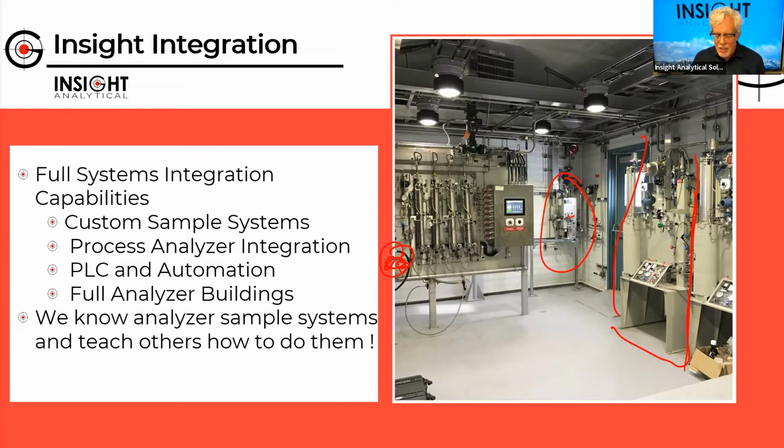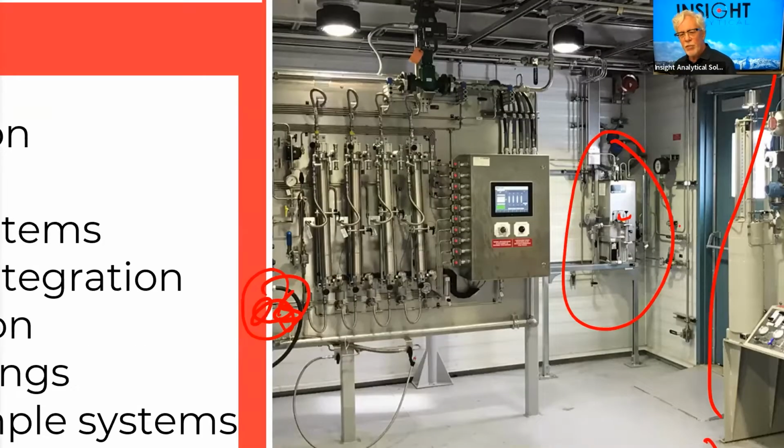There's 4 floating piston cylinders in there that are being controlled by the PLC, and the PLC can actuate when samples are getting taken and grab samples being taken, automate that process, correlate it with the spectral data that's coming from the analyzer. So there's a lot going on in this building, and it's one of my favorite ones to show.